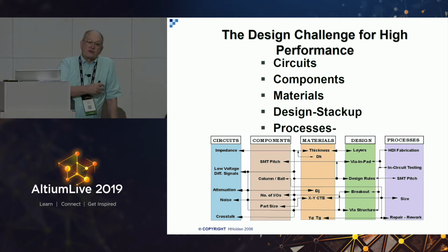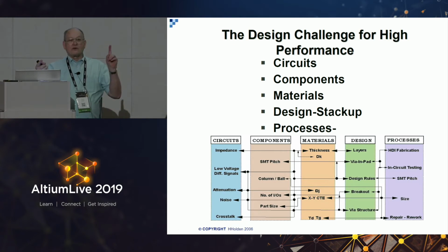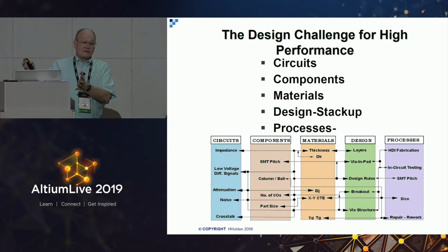And so you have these thermal modeling tools, three-dimensionally, that show what's happening to the temperature of the PC board and the cooling effect. And so there's quite a drastic range of temperatures on the printed circuit board. But if you go to the signal integrity tool, it assumes the printed circuit board is all at one temperature. And the modeling tool thermally just showed that there's a 50 degrees Celsius difference across the PC board.